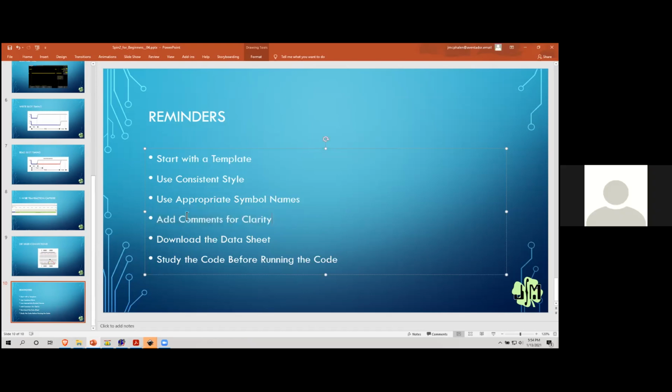Neat. Yeah. One of the things that's also really nice about the Propeller versus Arduino is that you can often take a project where they needed to use 3 or 4 Arduinos and do it all with one Propeller, right? Especially more so with the P2, because every pin can be an analog pin, and a lot of times you're limited by analog inputs on the Arduino because they only have a few. We have 64, right? Well, now we have real analog output too.